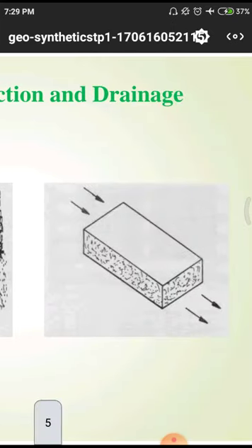In the first place, on the top of the surface we have coarse materials, and in the bottom structure we have soft clay, so those two kinds of materials will be separated by using this geotextile layer. This is the major function of the geotextile, to separate two different materials and two different layers. And how will those act? We have the direction of these arrows from one point to another point.